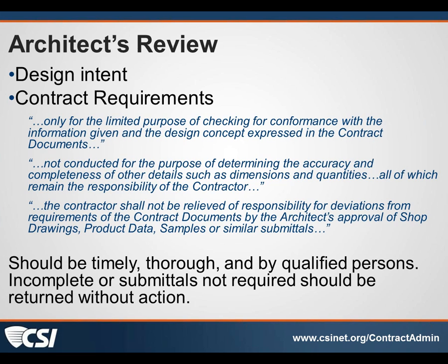And a lot of contractors want to argue, well, you approved the shop drawings, and I say, yeah, I did approve them, but the shop drawings don't change the contract requirements. You're still obligated to do what was in the contract. I may have missed catching the error in the shop drawings, but I didn't create the error in the shop drawings. Your sub or your supplier did, and you did by not catching it in your review. I'm not responsible for their error. I may have missed their error, but I didn't create it.